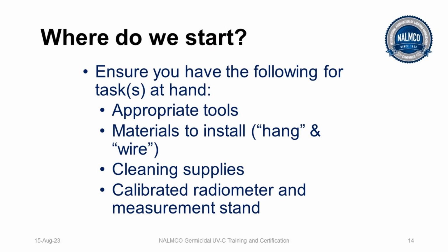Let's go back to where do we start? Ensure you have the following tasks at hand. Do you have the collection of appropriate tools? Do you have the materials to install, and we'll say hang or wire, the fixtures or luminaires? Do we have the cleaning supplies available? Do we have a calibrated radiometer and detector and some type of measurement stand? And as you heard from Dr. Sliney earlier, the standard eye height measurement is taken at 1.8 meters or roughly 6 feet.